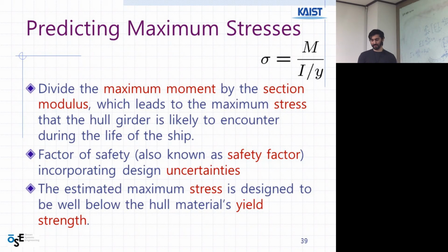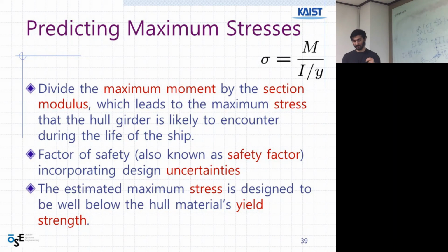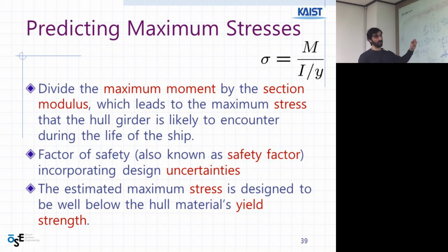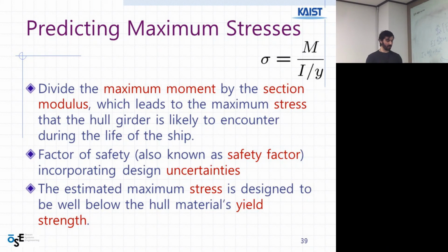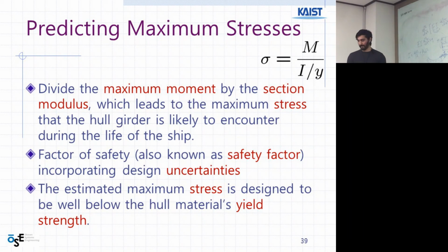One definition is called the realized factor of safety. It is when you divide the absolute strength of the beam by the actual applied load. The larger the value, the better. One more is the required factor of safety. It is imposed by law, standards, and so forth.